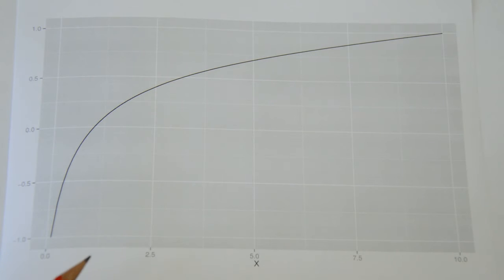So let's say we're applying a weak signal. If we're applying a weak signal, we're going to be somewhere in that range because the signal is weak, it's low, so that's a small x. And that weak signal changes by a small amount, which means that we're moving to the right or to the left. That will result in considerable change in the output because we're exploiting the steepness of this graph in that lower range here. So we have high sensitivity for weak signals.